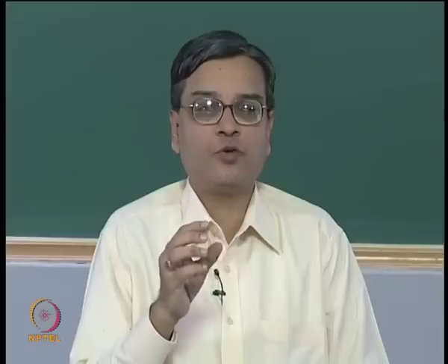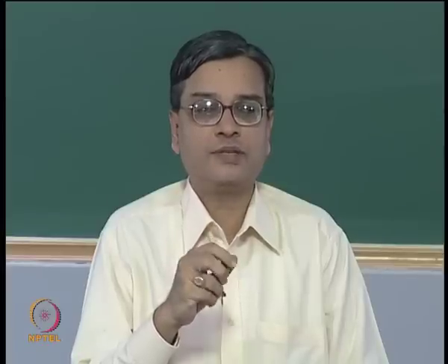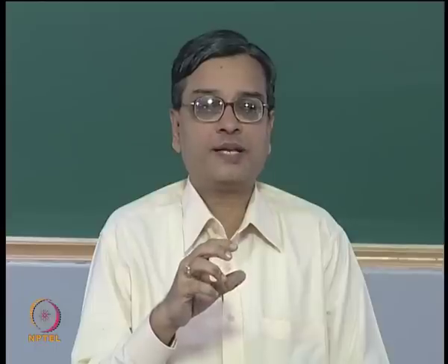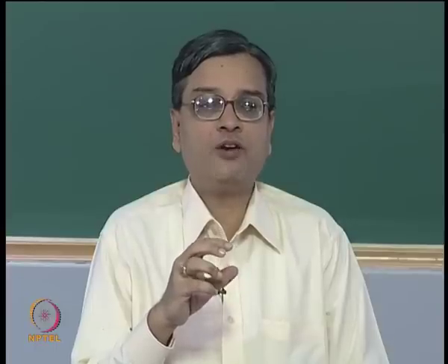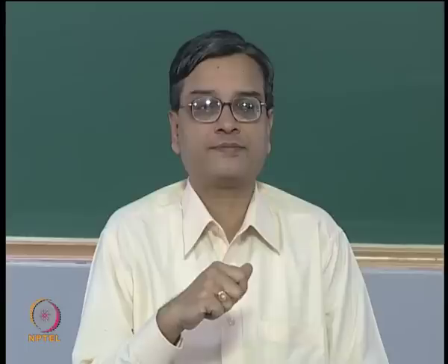And I said most fracture theories still focus on the importance of the singular term; only some of the recent theories really look at the second term. So, from that point of view, for the rest of the course we would focus only on the singular solution, and the focus becomes finding the stress intensity factor for a variety of geometries.